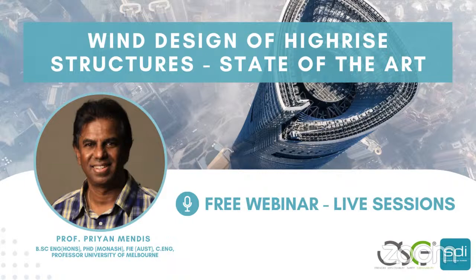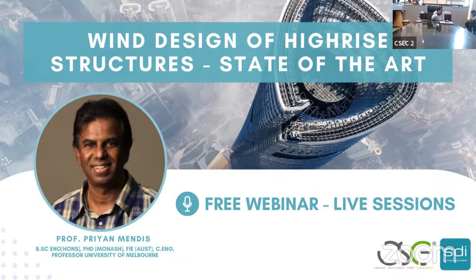But to engage other columns, you can use the belt truss, because an outrigger is connected to only one or two columns. To engage all the other columns in that strip, we can use the belt truss, so that they all work together, not just the one column the outrigger is connected to.